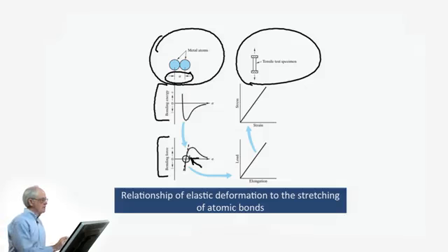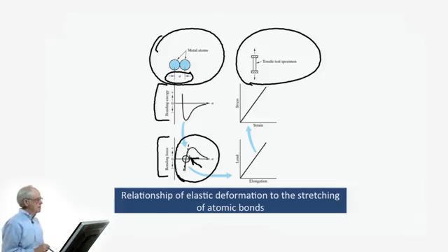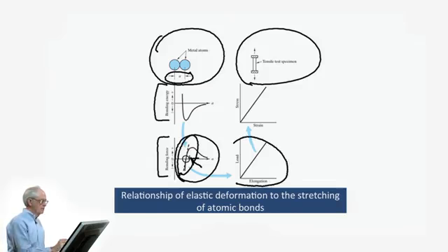And so, even though this is a highly curved plot, this bonding force curve, again, we emphasized when we were talking about this early on in our discussion of atomic bonding, reviewing those basic chemistry principles that we'd likely seen before, that the tangent at this point is a nearly straight line. So that explains why the overall load elongation curve is straight. Again, it's just a macroscopic scale manifestation of that interatomic bonding,